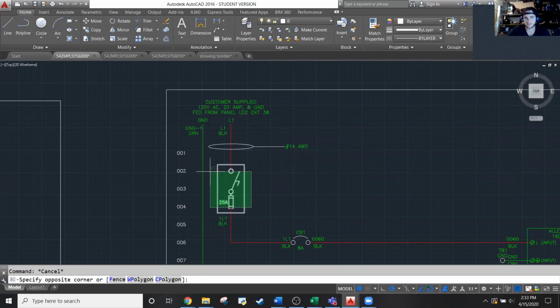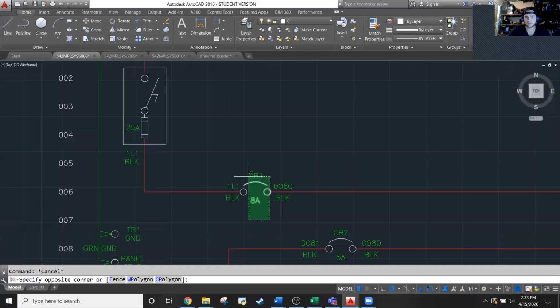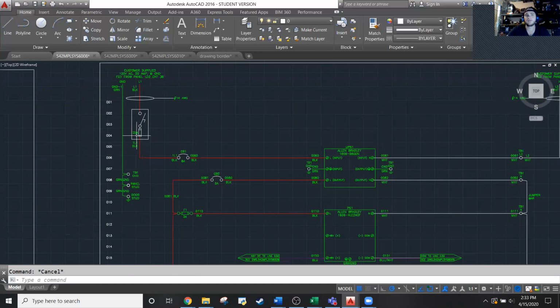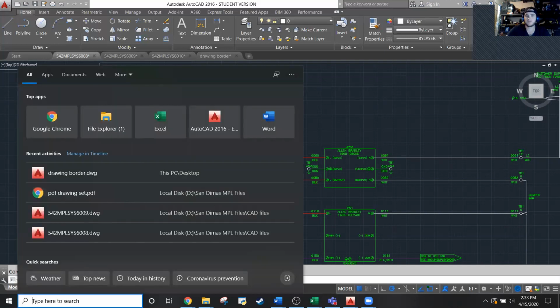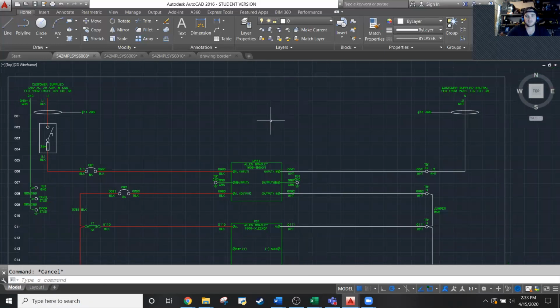We show there's a main disconnect on this panel for the power. So this was a giant physical switch. We just have a breaker in our panel, which is shown by this symbol here for circuit breaker. But similar concept. You want a single disconnect point that kills power to your entire panel, so you can shut that off easily if there's a dangerous situation and sparks are flying.